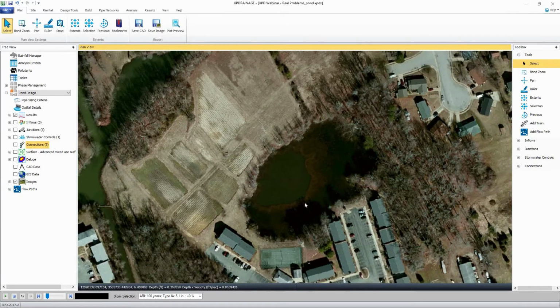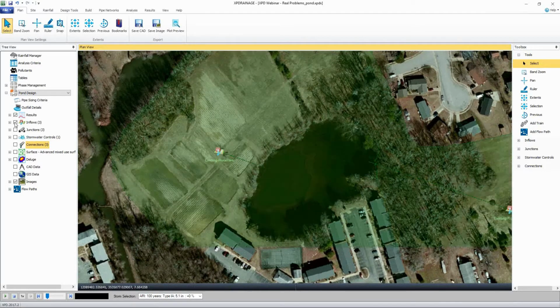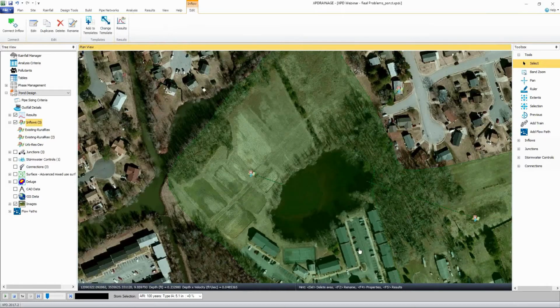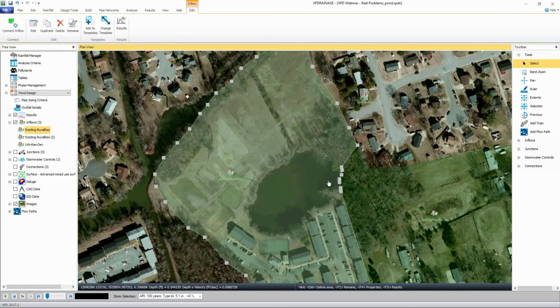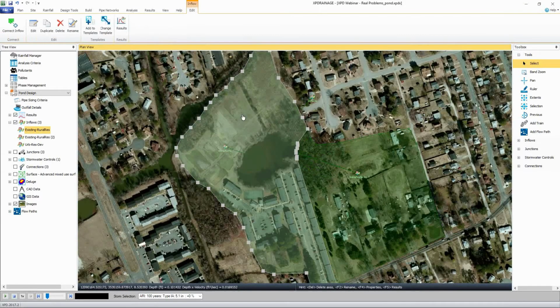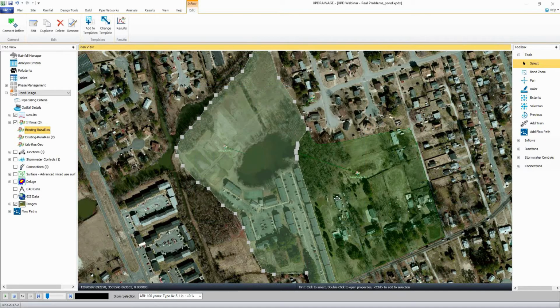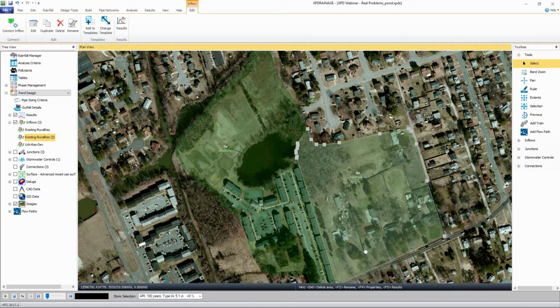So we have one pond that, as we find here, is going to have different inflows into it, right? So here is one catchment that I delineated. You see that this whole area really does drain directly into the pond. One thing we can do, we can check out this catchment, this inflow area, and you'll see that the area that I've drawn is automatically updated, and so on and so forth. So here's one set of inflow into this pond. Here's another inflow area. Again, I've delineated this zone. This is going to drain all into this one corner of our pond.